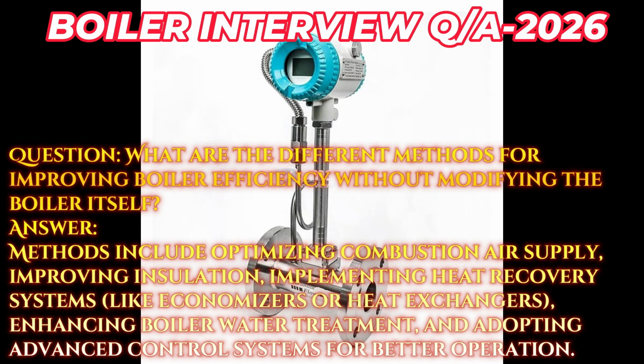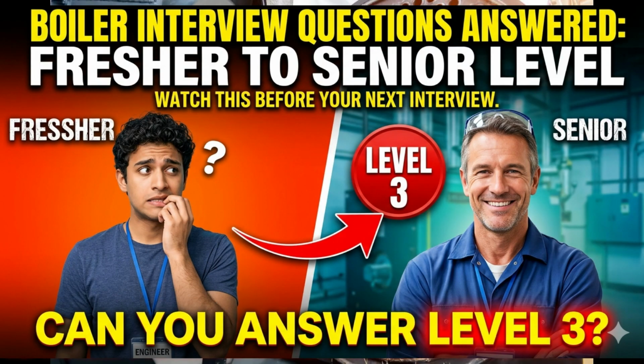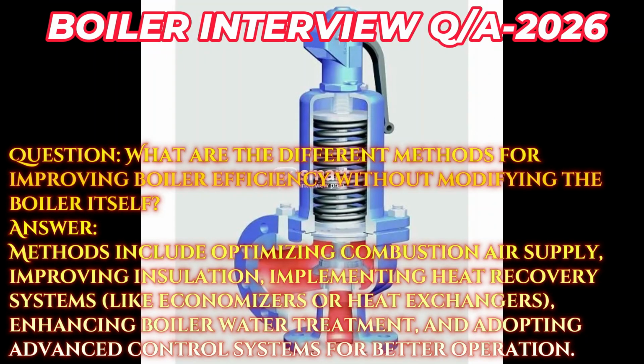Question: What are the different methods for improving boiler efficiency without modifying the boiler itself? Answer: Methods include optimizing combustion air supply, improving insulation, implementing heat recovery systems like economizers or heat exchangers, enhancing boiler water treatment, and adopting advanced control systems for better operation.